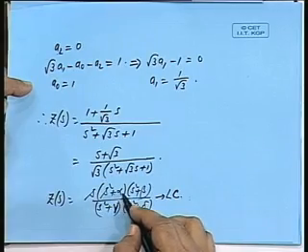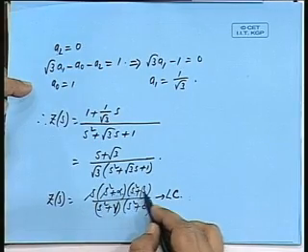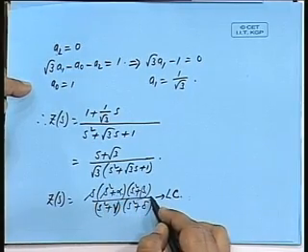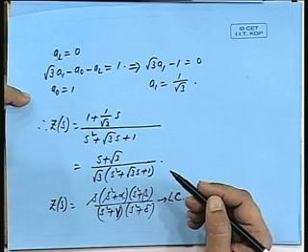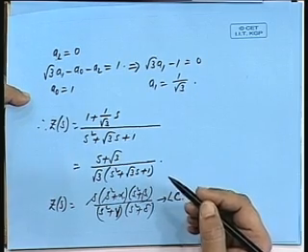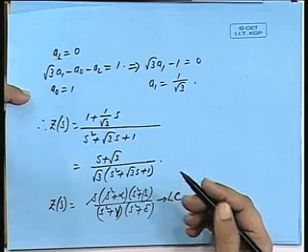If Z(s) is having real roots, s plus alpha, s plus beta and so on, and if they are interlaced, then they can be either RL or RC depending on whether the pole is closest to the origin. If the first one starts with a pole, then it will be an RC.